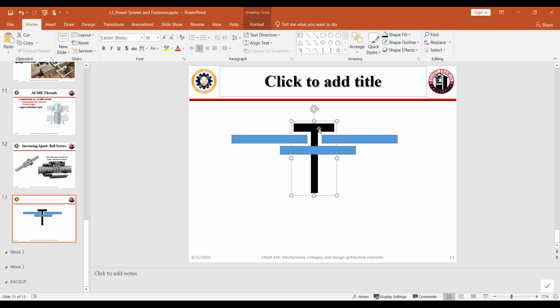As a result, because that's how I'm assembling this, I do not want the screw to thread into this first piece of material, colored a little different, distinctly different, because I want that to be as firmly clamped as possible. If it's threading into that guy, as well as the guy below it, how well everything's going to clamp is limited by how far the two materials are each moving relative to one another. It's going to be an absolute mess.